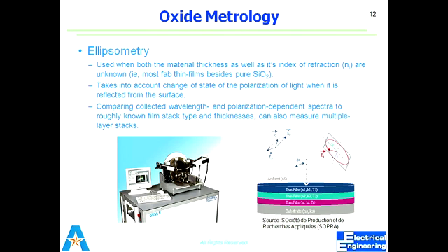Okay, so in ellipsometry, what happens? The phenomenon is actually the same: you have the wafer surface, and at a specific incident angle, which is fixed. In our case, it's 70 degrees in the ellipsometer that we are using in the lab.